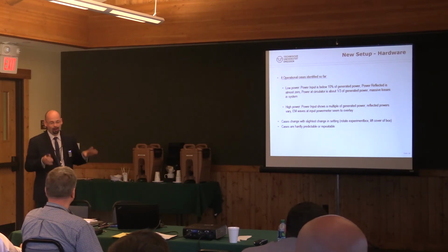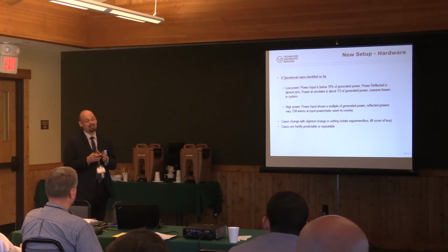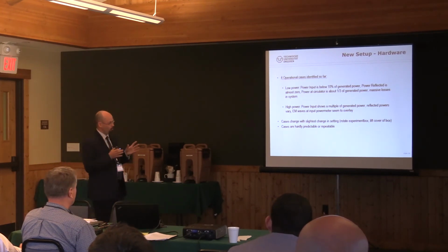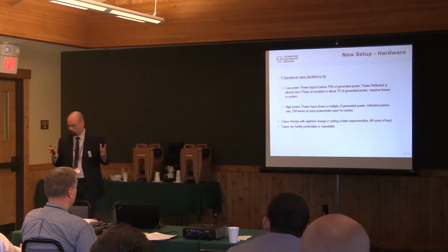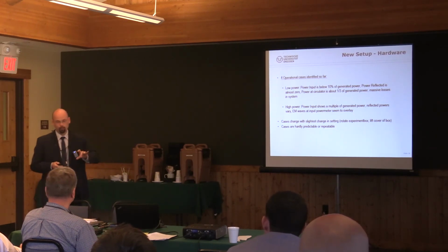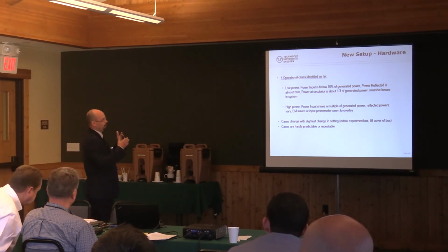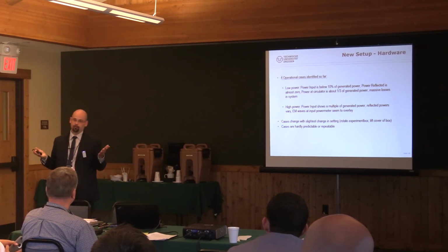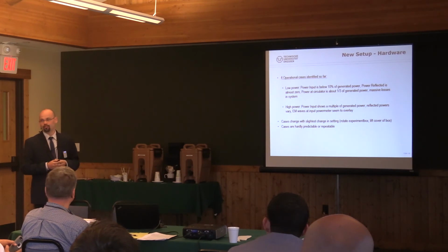Well, I know that my amplifier only produces the power I am commanding. So where does the power come from? Nowadays I think it's just a matter of very lucky overlaying of my EM waves inside my oscillating system, so that exactly at the point of my power meter, at my bidirectional coupler, the waves add their power to each other and the power meter just sees the sum of power. Well, that's the thing Roger Scheuer said: don't trust your bidirectional coupler.